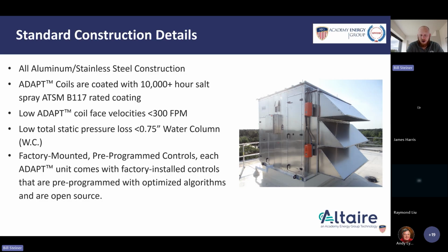It also helps with air pressure drop, right? Part of our mission here is to save energy. It makes no sense to run that coil any faster than we have to and take a penalty by way of air pressure drop. Lastly, because we're wringing a lot of moisture out of the air, the slower we run that, the more we reduce our risk of carryover. So if we're running at 500 feet per minute, there's all this crazy water coming off it.